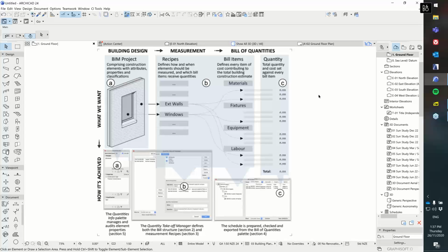It also allows you to export all of your measurements and criteria to other projects, so you can set up a standard list of measurements that you're interested in and then import that into all of your other ArchiCAD projects so that you're getting the same set of measurements out of every project that you work on. So those can be imported and exported, and obviously you could just build them into your template as well if you wanted to use them in all your projects. So that's the main areas that our Quantities tool is aimed at helping you.